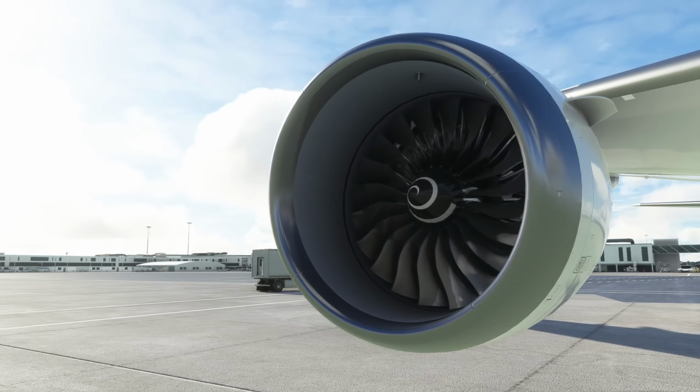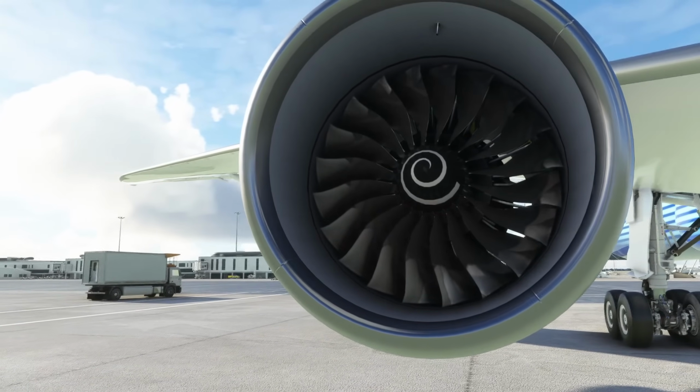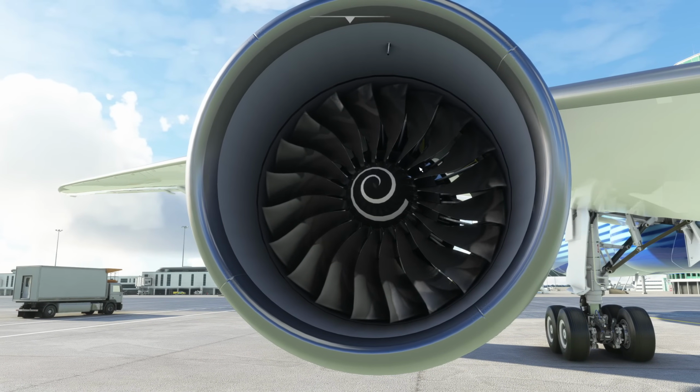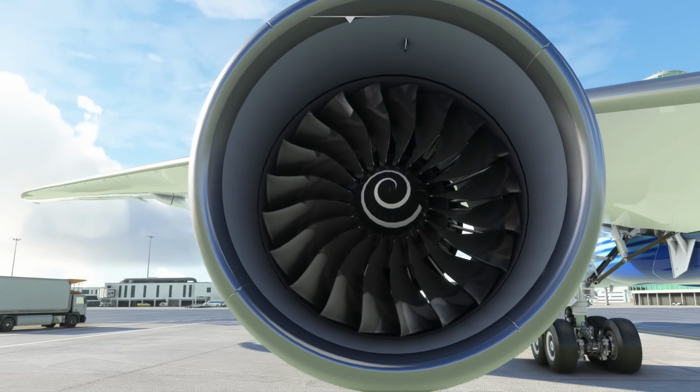And what we've got in the intake of this engine is, again, really, really similar to the Airbus Neo engine. Big fan, high bypass ratio. So what I mean by that is the core of the engine in there is where the actual air goes in and gets compressed and ignited and sent out the back. And all of this stuff around the side is just cold air that goes through this fan. Big, and that's called bypass air. So you want a big bypass ratio these days, it's what they go for efficiency, and this aircraft is very efficient.